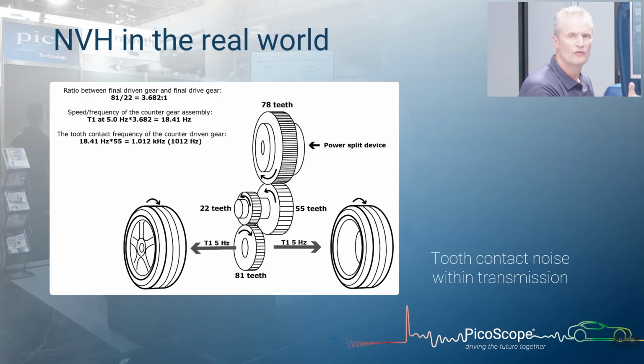And that's very powerful for support teams and engineers alike, because they will know the frequencies of these gears. They will also know the tooth count, so they'll know the tooth frequency. So again, great information that we can present to engineers and technical support staff that supports the customer complaint and aids with diagnosis. And in this scenario, the transmission was replaced and the noise level, while still present, had been reduced dramatically.